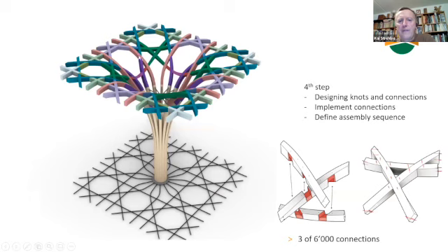So now we have the segmentation, and on the segmentation, we are working with the joints. We work with lots of different kinds of joints, like very traditional wood joints. In the Cambridge Mosque, like this part here, we work with normal lap joints, but also with steel connections, with steel plates, and all kinds of connections.